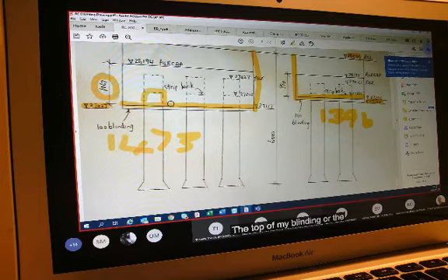That height is given to me when I have a look at the levels. The levels would then be 27203 minus the top of my blinding, or the bottom of my pile cap, 27127, and that gives me 76 millimeters. So I will then multiply that by 0.08, what needs to be deducted. That height there is 0.08, and that is times pi times 12 of them.